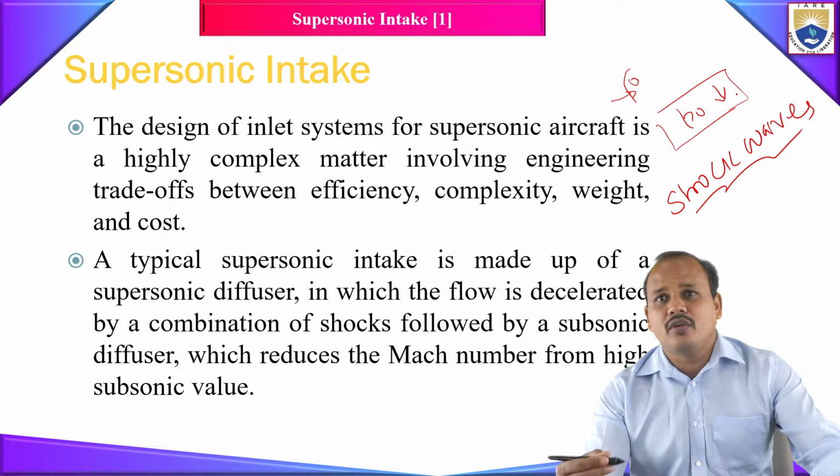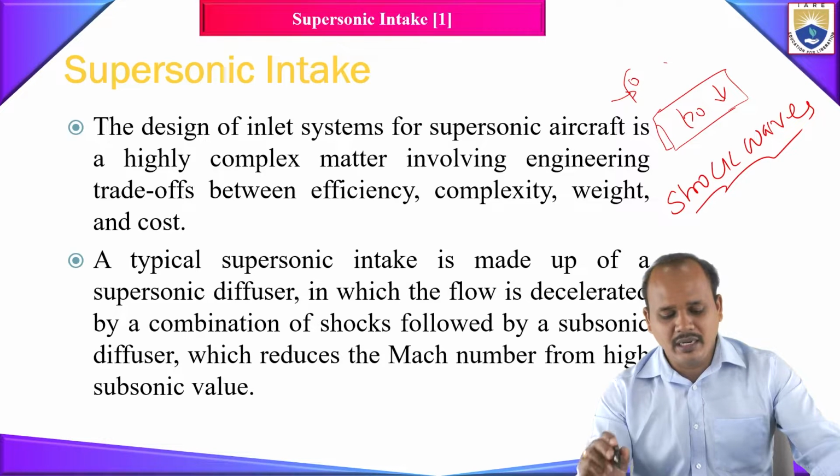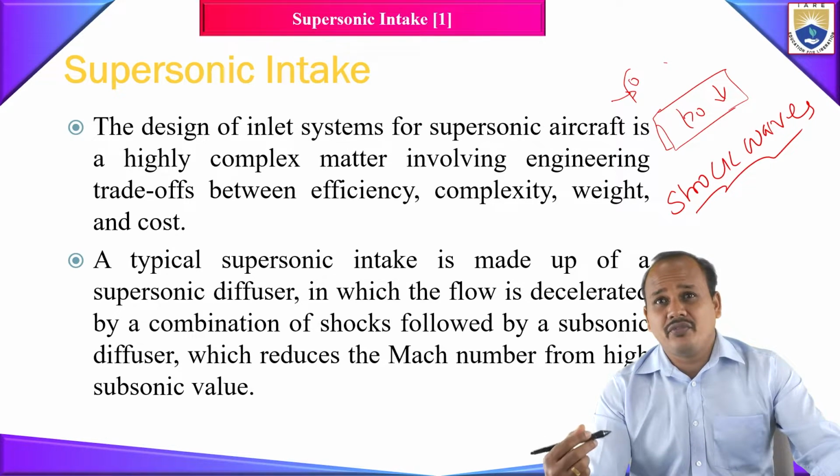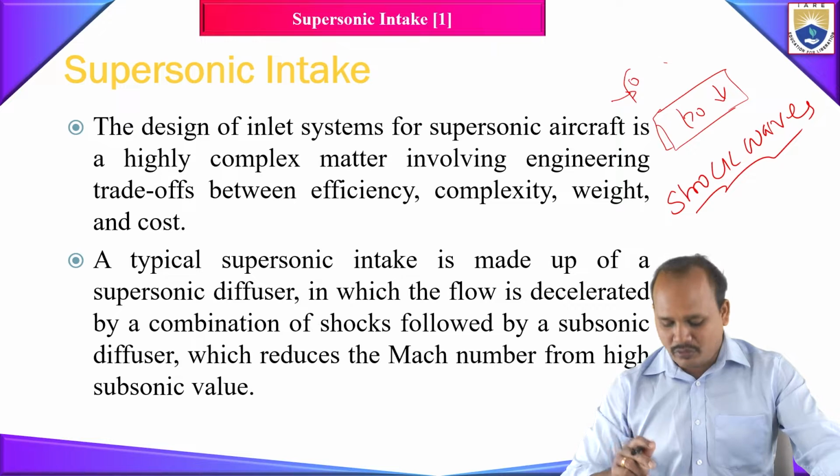But when you go for a supersonic intake, in addition to flow separation and frictional loss, the formation of waves also contributes a certain amount of loss. So obviously it is very important to properly design your supersonic intake so that it produces the weakest form of shock wave. A weak shock wave means that when the flow crosses it, the loss in total pressure is very, very small. That's why I said the design of a supersonic intake is much more complicated and difficult than that of a subsonic intake.